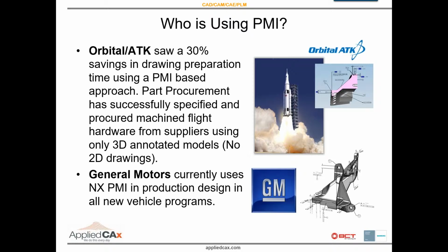Who's using it? Orbital ATK and General Motors are two big recent users of 3D model-based definition. They've gotten their supply chain up to speed, which is likely the biggest challenge you're going to run into: getting your supply chain to accept a new type of data set. Traditionally, we share a STEP in a PDF, or if you're running in SOLIDWORKS, you share the SOLIDWORKS part file and drawing file, things like that. The idea is that you want to have just a single part file, a single data set.